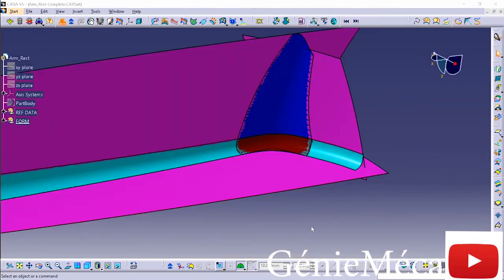When you're designing your Class A surfaces, there are three things you have to consider: your primaries, your secondaries, and your tertiaries. Your primary slabs are your biggest, most general shapes. They basically capture most of the intent. Your secondaries, these blue surfaces here, are typically your blends between primary surfaces. These primary surfaces have a nice general flow capturing the largest slabs, overbuilt geometry. So it's easier to overbuild and come back and trim things up as necessary.